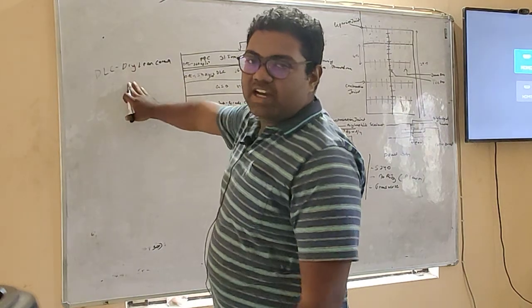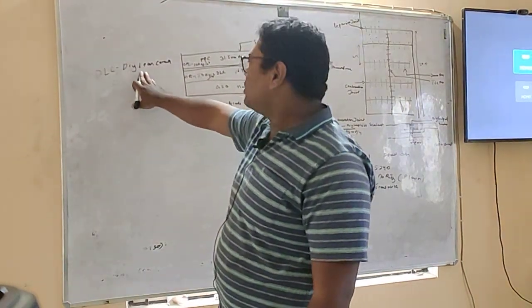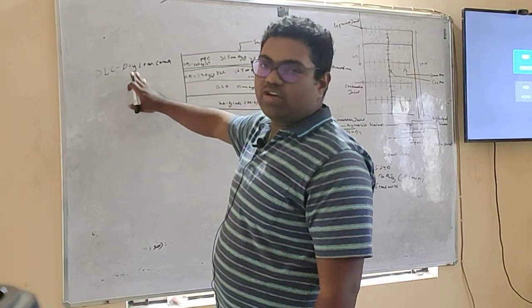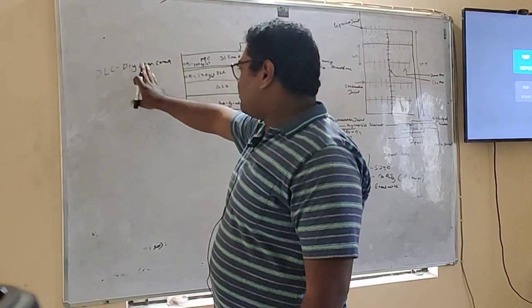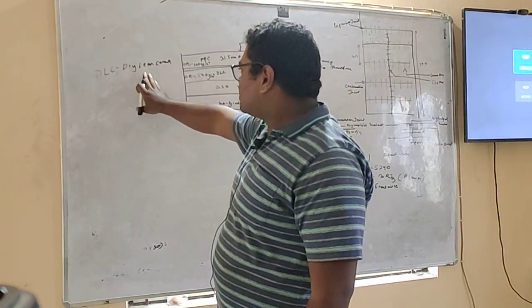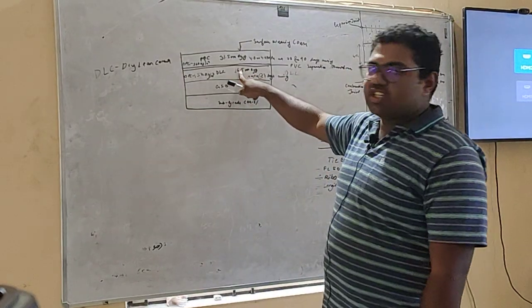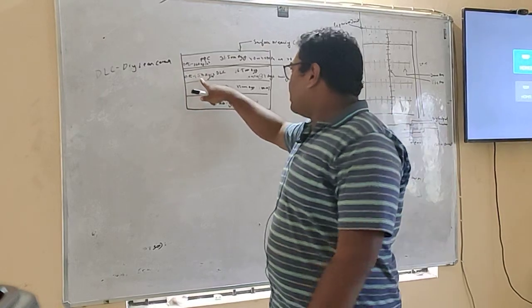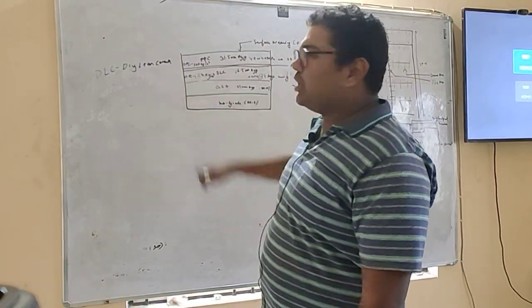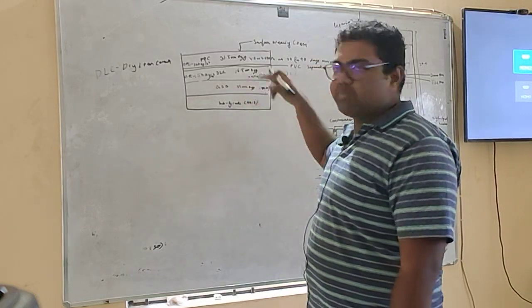It is procured from an RMC plant and it is transported using dumpers. We can lay it manually or with the help of an electronic paver machine. After laying it, we must not allow vehicles to move over it, otherwise it will damage it. It has an aggregate size of 26.5 mm and the OPC content must be around 150 kg per meter cube. And after 7 days of curing, the strength of DLC should be around 10 megapascals.